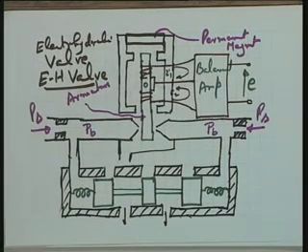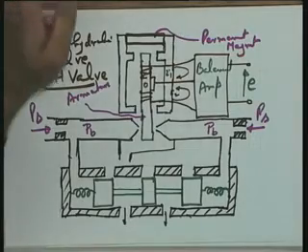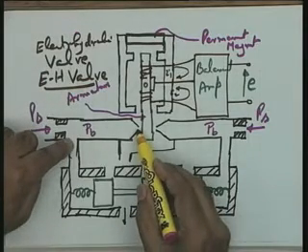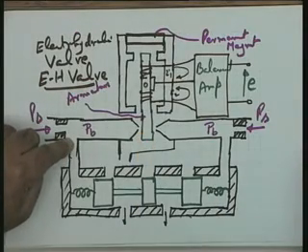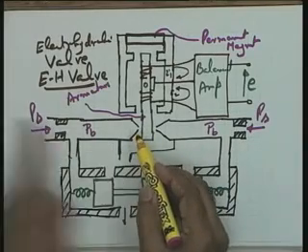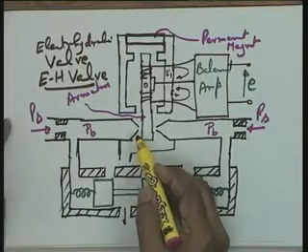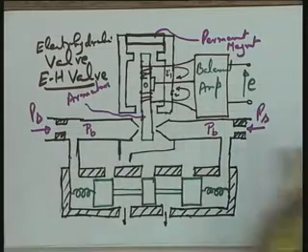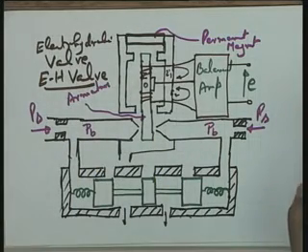Well, you have said both increase or decrease, or clearly decrease? Decrease, yes. Please see, because this particular point is open to the atmospheric pressure, and if you close it, PB goes towards supply pressure. So it means PB is changing between atmospheric pressure and supply pressure. Atmospheric pressure is taken as 0 gauge.